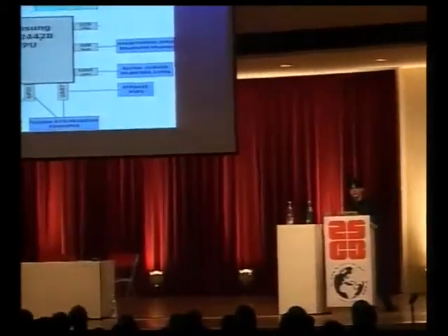And in that single package, there is not only the system on a chip, but also the flash and RAM memory. It's what's called a multi-chip package. So you have multiple dies inside one physical package to save what's called PCB footprint. So you save space on your board design.